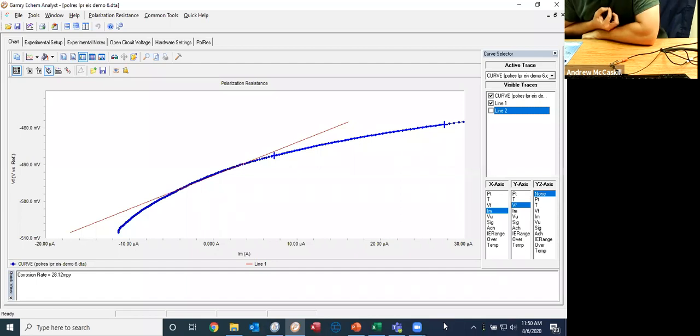For example, compare the potentiodynamic scan that I mentioned before, where we're scanning over a voltage range of 1-2 volts as opposed to just a few millivolts. That is destructive, and you certainly are going to change the surface of the material. But I don't see LPR as a truly destructive technique, as opposed to a lot of the other experiments where you vigorously polarize the surface, as opposed to just enough that you can get a measurement.